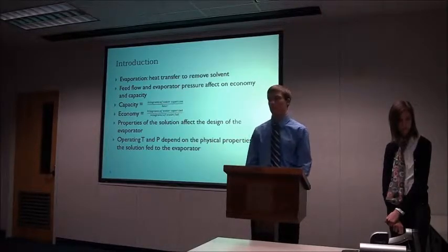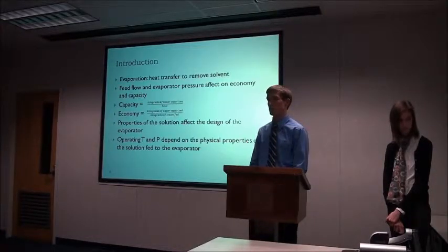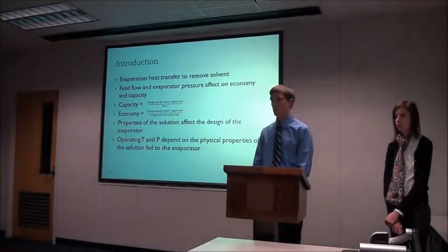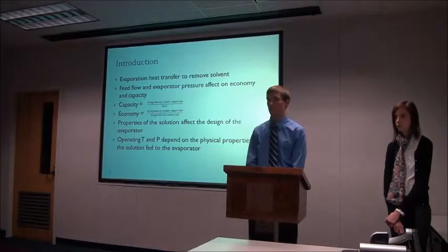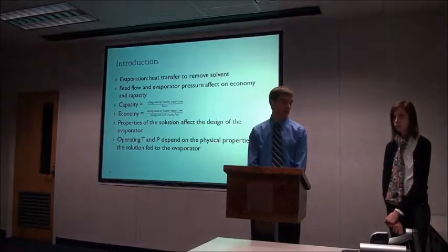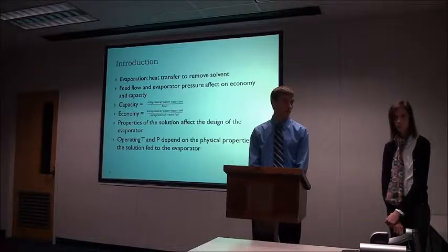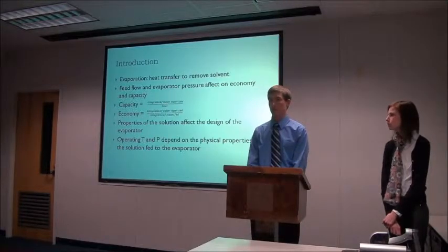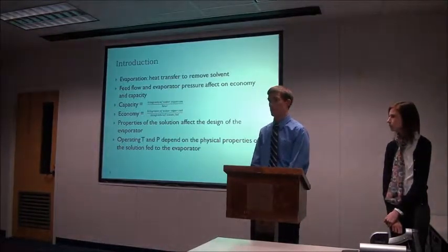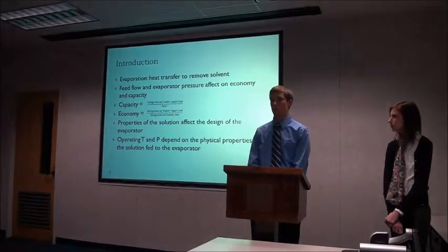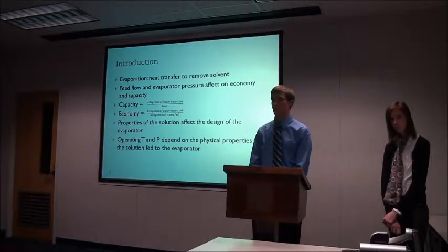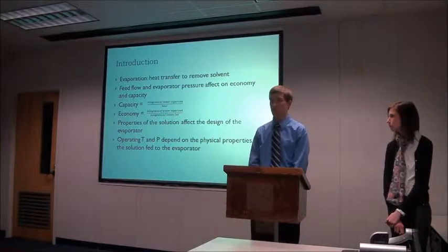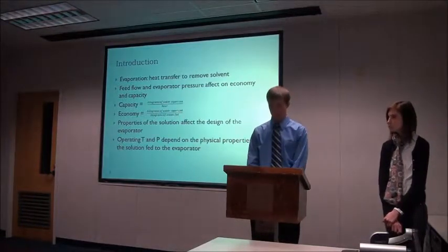So density, if you need a different design for density or viscosity or anything like that, you could have it in a vertical direction or you could have it in a horizontal direction, depending on your purposes. The other factors affecting the evaporator are the operating temperature and pressure based on the physical properties of the solution. So depending on if you need a higher temperature to evaporate the solvent out, or you can maybe lower the pressure in order to increase the saturation pressure, so that the temperature would increase for when it would evaporate.